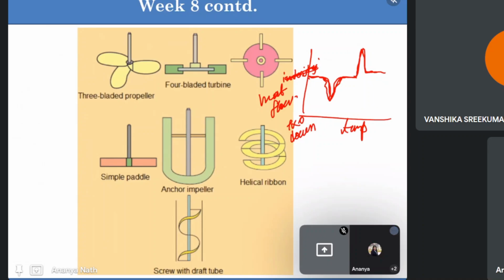Yes, exactly. If it is released in the form of heat, it will increase the temperature inside the material. In the case of strained material, the temperature will increase. But as you said, the strain is so high inside the material, there are so many dislocations moving inside it. Whenever you increase the temperature, the strain will be released in terms of heat, and after some time, if you are still increasing the temperature, the heat will start absorbing. Heat will be absorbed, and this is why you get this endothermic peak.